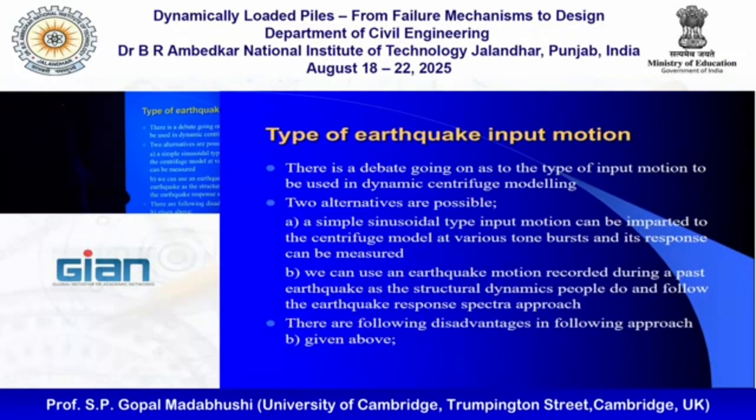Whereas if you put sinusoidal motion, it is all quite clean and you can track if the natural frequency of the soil is changing, we can track it. So both are true, and many people, even with sophisticated shaking tables, still use sinusoidal motions where you want to study the fundamental behavior.